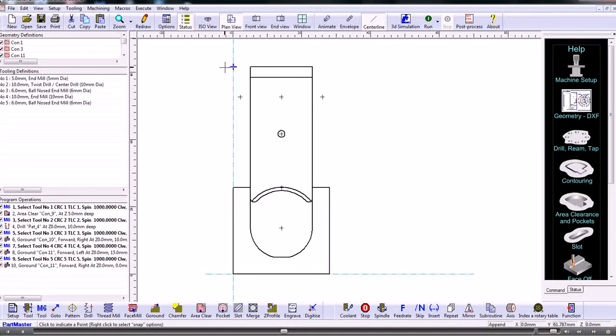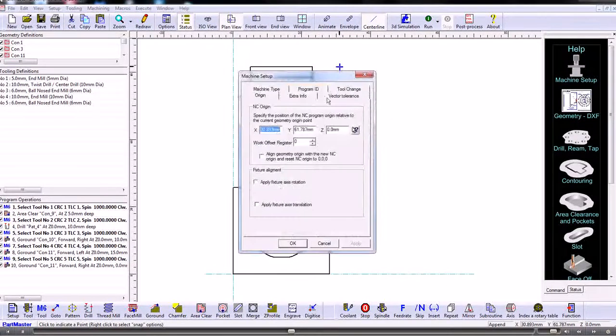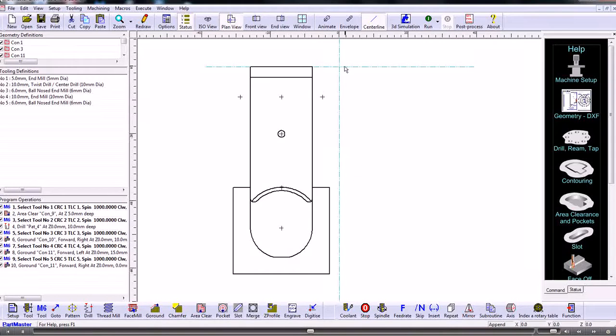So I might want to choose that far right hand corner there, for instance. So that gives me the coordinate of where the extent of that geometry is, and now if I check that box, that resets the geometry to that original top right hand corner. The reason it's over there is because there are some other contours which I've temporarily switched off just for clarity, but that's why it's chosen that one there.